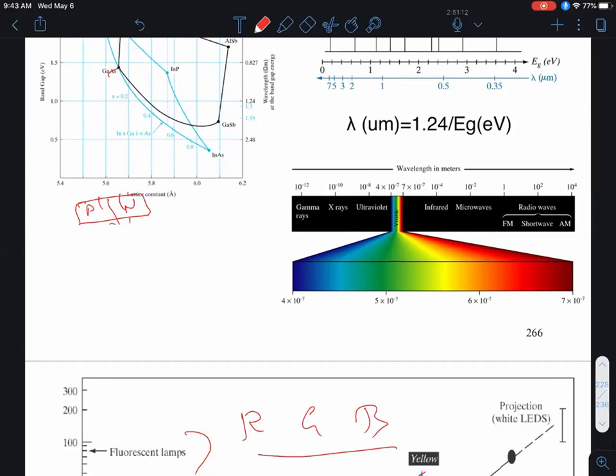in a laser, you take a PN junction and you have to bias it very, very strongly forward biased, okay? So that you inject, see, that's my P side, that's my N side, so I'm injecting holes this way and electrons this way. I inject so many electron hole pairs that you get something called population inversion. This is just for fun, you're not responsible for this in the exam, okay?